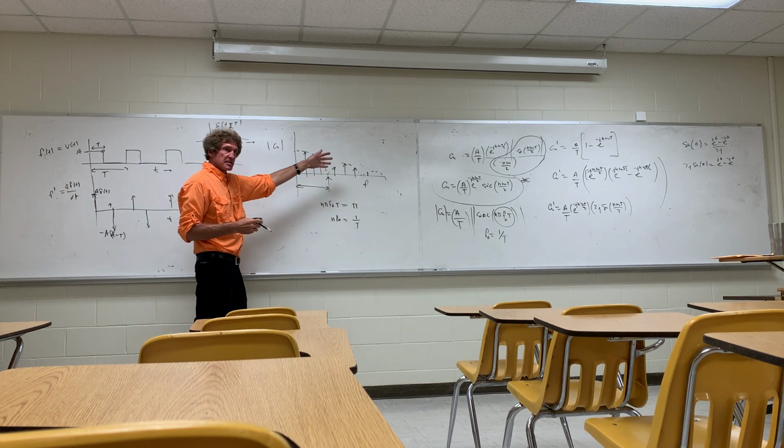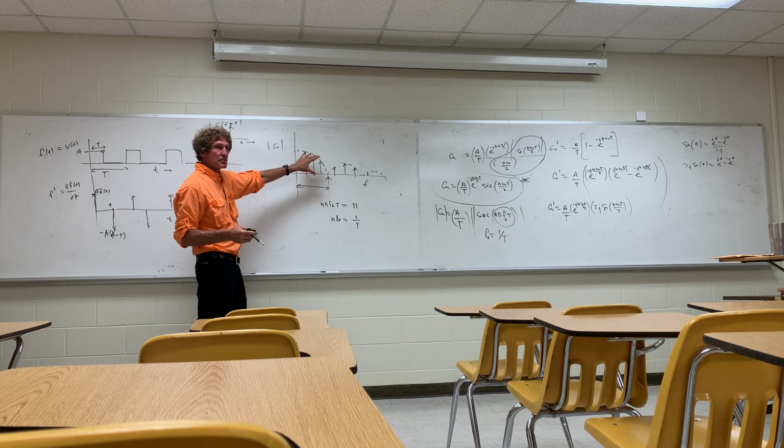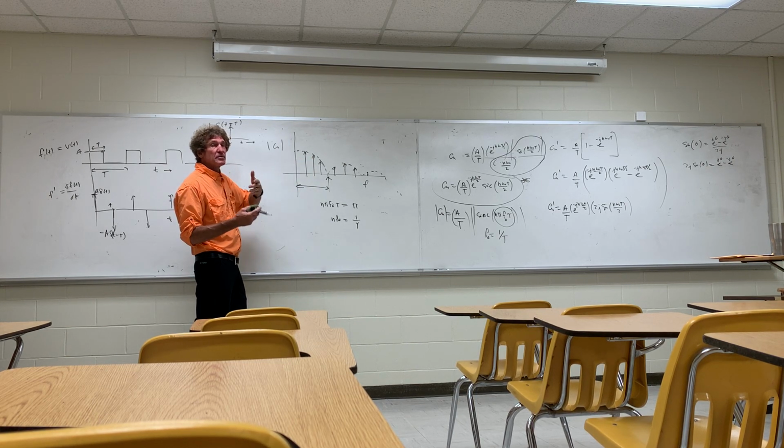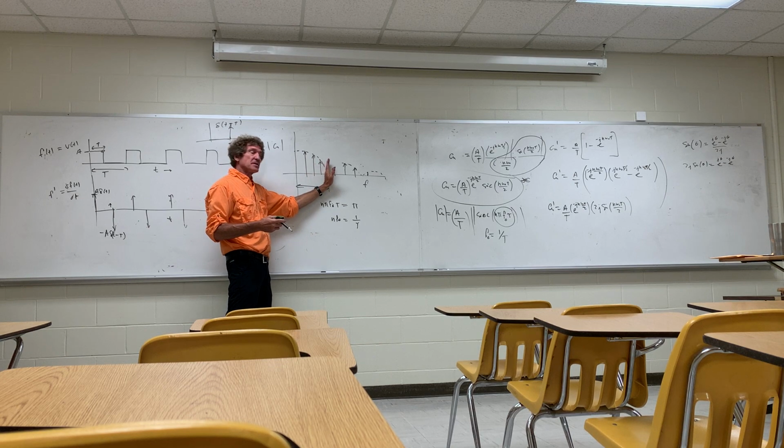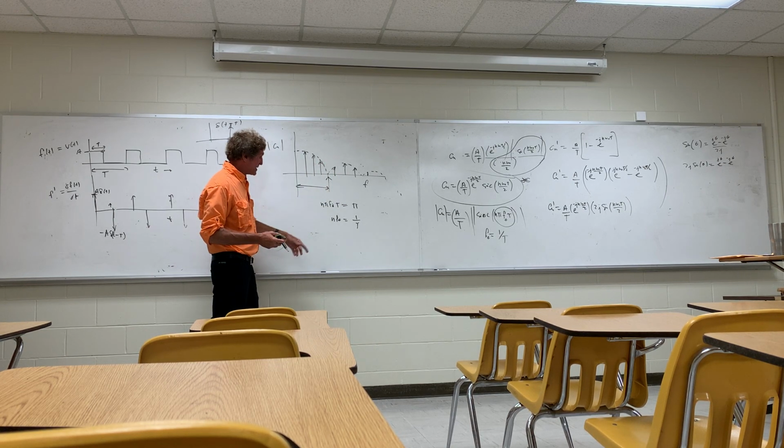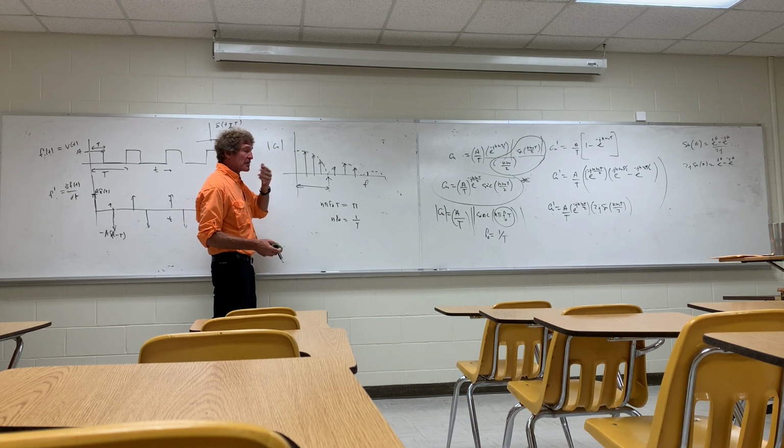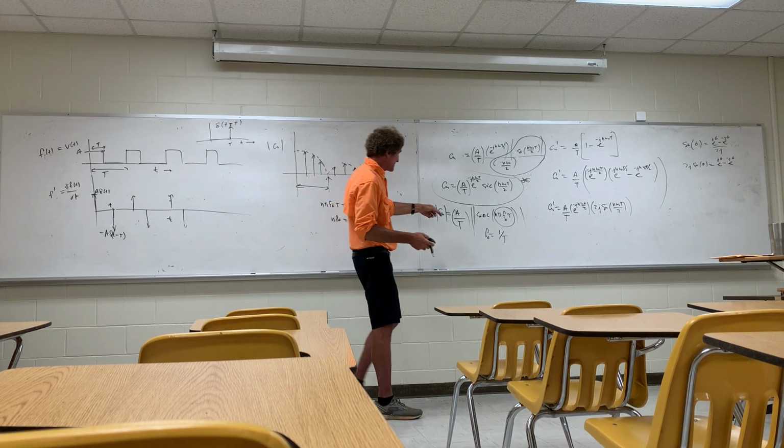There are some high frequency components, but this really is the important range when we're doing any type of work with radar, EMC analysis, anything that involves digital signals, and you want to talk about the bandwidth or the frequencies you have to be concerned about. They're limited to this point in the frequency domain. And that point is simply n f naught equals 1 over tau, 1 over the on time. I'm going to spend more time on this, but the power is actually proportional to the squared values of these C of n.